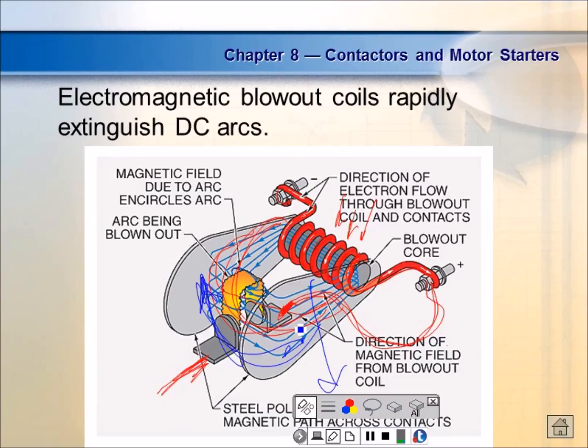So if you ever get into some high current DC stuff, especially if you go out to U.S. Steel, a lot of your new cranes are running off AC motors because AC motors are so much cheaper than DC motors. The biggest problem we have had for years and years is that with AC, we couldn't control the speed of the motor. An AC motor wants to run at something below this, but it wants to run at 120 times the frequency divided by the number of poles.